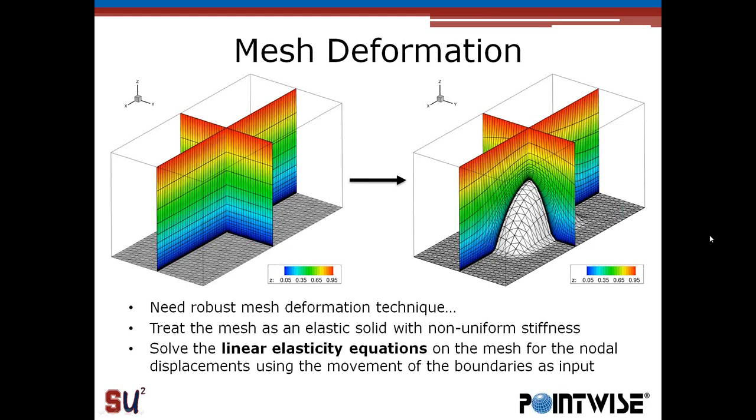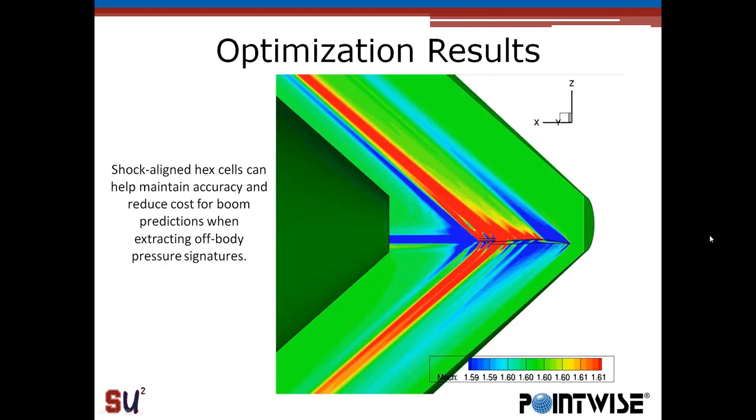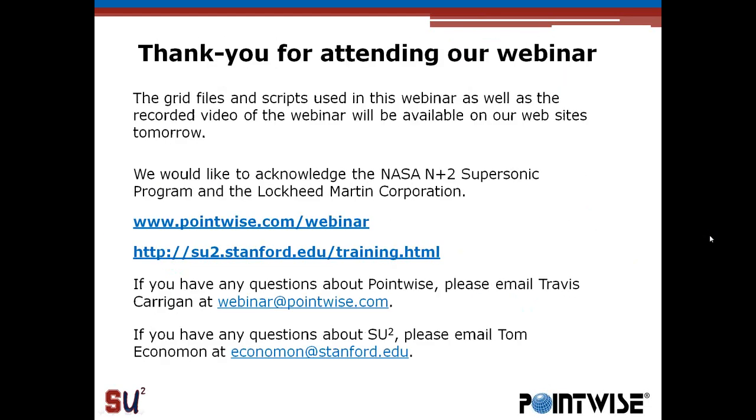If you step it in increments rather than moving it all the way into place, and you say solve the deformation problem in 5 or 10 step increments, we can get to some very large deformations. So we found this to be very, very robust, and it's been very good since we put it in. We've done Euler design and all sorts of things. So it's been quite robust to large deformations. Okay.